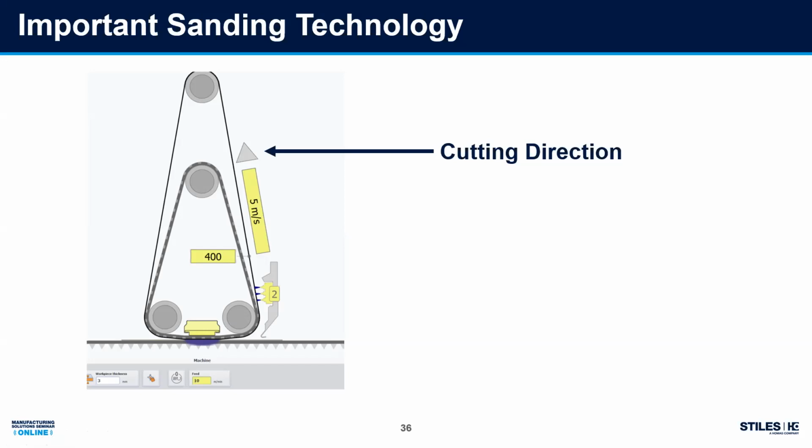And especially when we sand veneer, this can be an important consideration because oftentimes the way veneers are laid up, you have multiple different pieces, leaves of veneer, spliced together, and you don't want the fibers to lay down differently. So if you cut in multiple different directions, much like mowing your lawn, you cut those fibers very short and you're left with less fiber rays in your finished process.